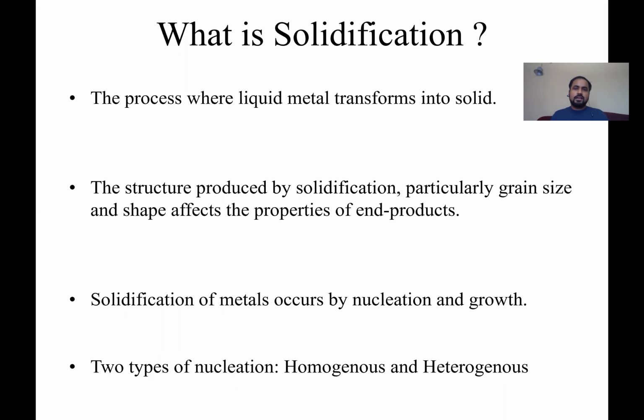All right. So now we got the molten metal, and you generally store it in some container, and it solidifies. So basically, solidification happens, which is a process of liquid metal transforming into a solid. Now, this solidification process can occur either via heterogeneous or homogeneous nucleation. When I say nucleation, that means a small grain will start to grow, and then its size increases and forms a grain. So the solidification process has two steps of nucleation and growth.